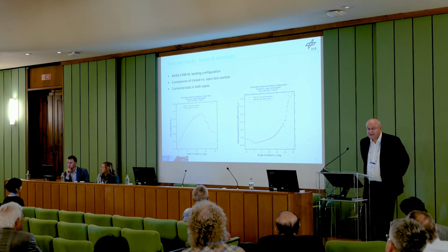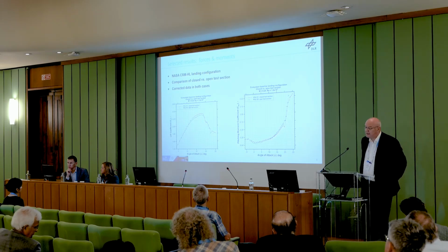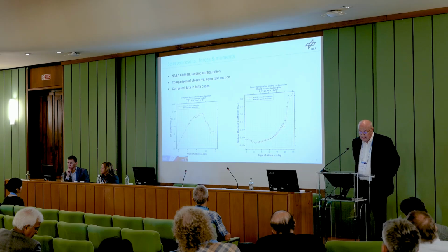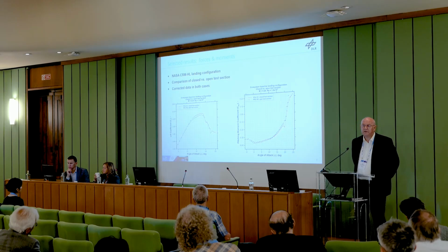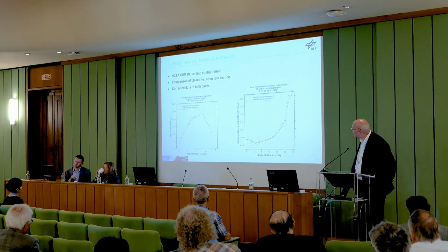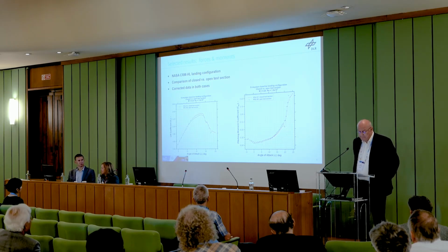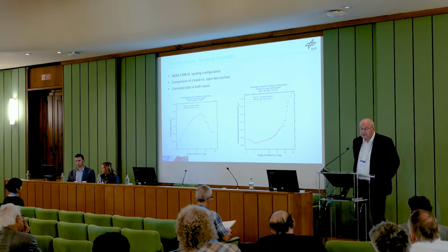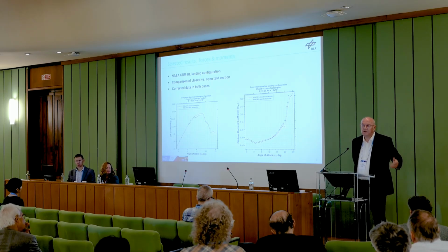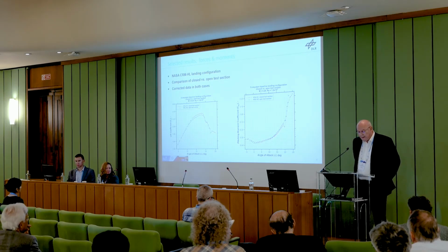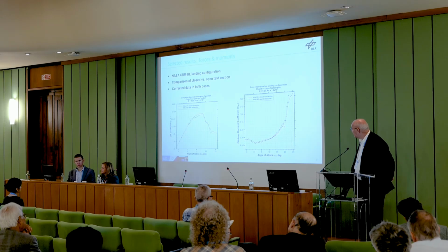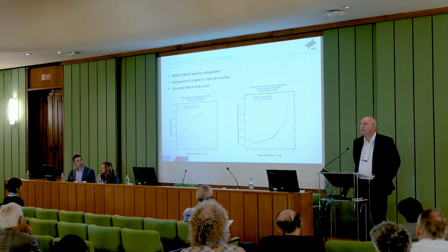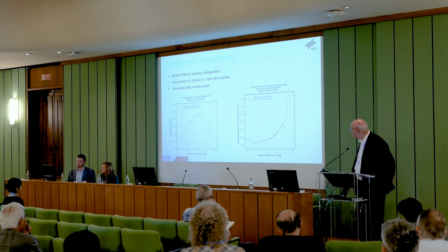Okay, next result for forces and moments is a comparison of the closed and the open test section for the NASA configuration. You see in red lines the lift curve for the closed test section, and in black the open test section. All data have been corrected for wall and mounting effects and jet effects. And the discrepancy, or the difference, is about 5 lift counts, which tells us that there is an effect, even if you correct. We corrected it classically following AGARDograph 109. In the linear range, data are pretty good, comparable. And as you usually test the open test section, as I mentioned, not for CLmax, but for acoustic reasons, where the linear range is of concern.